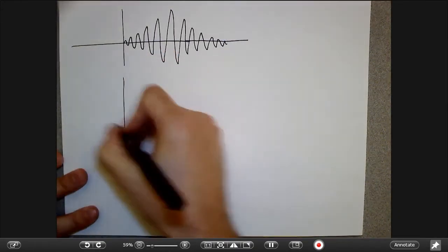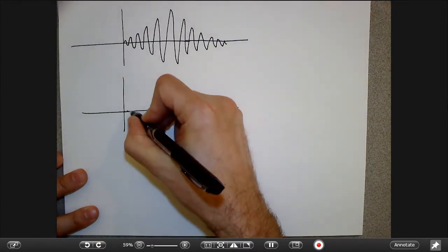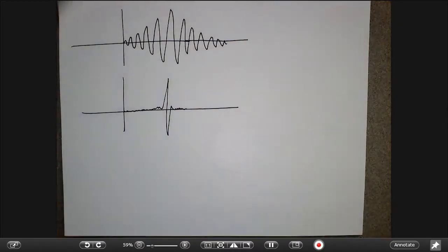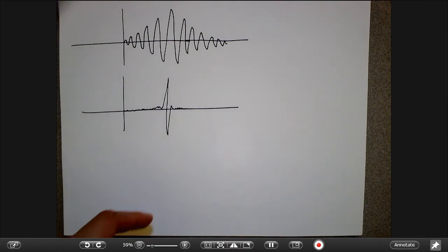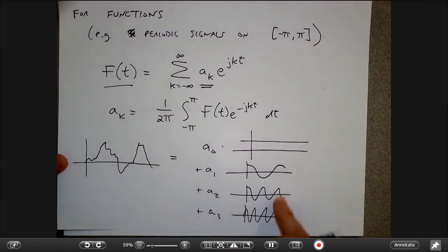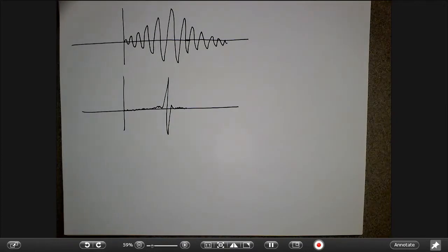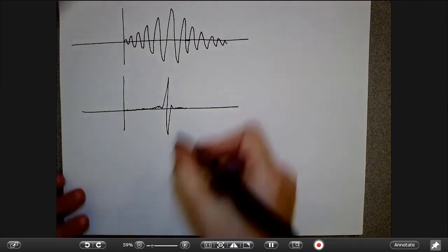Similarly, if I have a signal like this where nothing much is happening, and then I have some sort of a sharp spike and nothing much is happening again, Fourier series and Fourier transforms are awful at representing signals that are really spiky and really discontinuous, right? Because to make up this signal with a Fourier series, I have to make the signal up out of a lot of sine waves that have equal amplitude across the whole band, right? So it's going to take me a ton of Fourier coefficients to represent this signal. And these kinds of signals happen a lot in real-world electrical engineering applications, right? So when I turn a system on, I get this kind of transient from when the system goes on, then it settles out, right? So Fourier series are going to be bad at this.